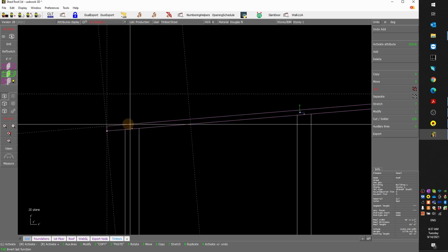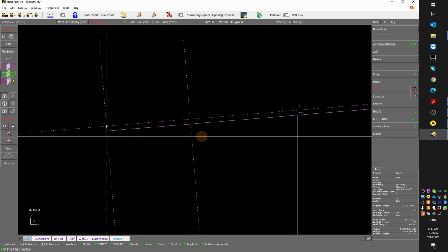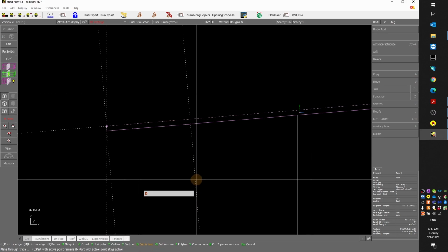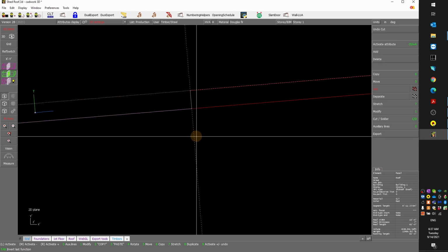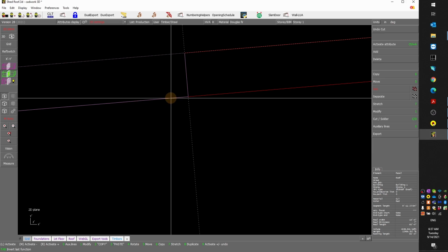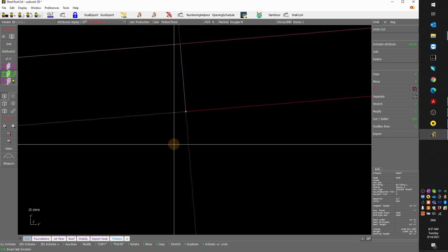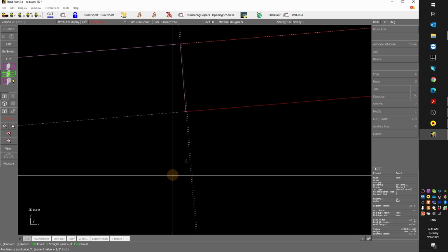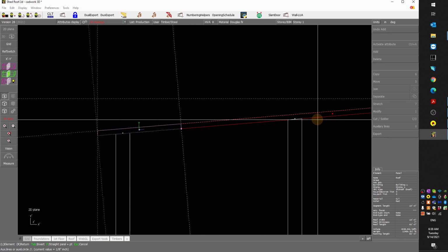So here I don't want to have an offcut. I want to keep both. So what I do, I press C D to cut in two, and I click here on the auxiliary line. So that's the first panel here. What I need is a gap of 1/8 of an inch. So I press E and I type 1/8 offset, make sure it's the right one, and I click here.